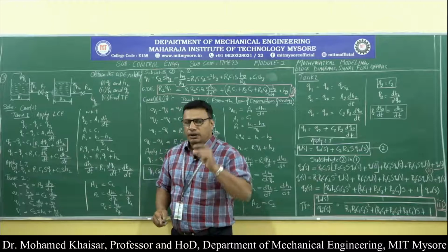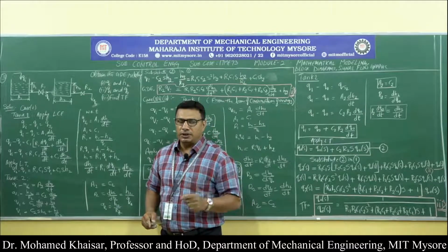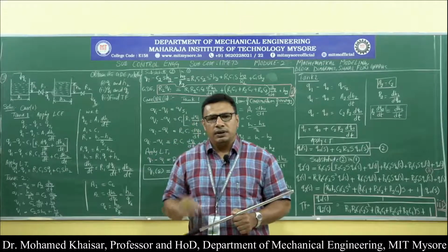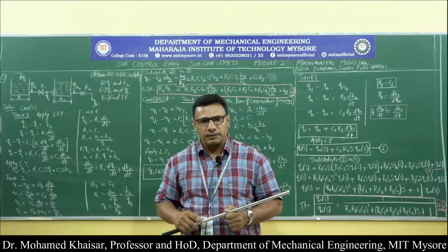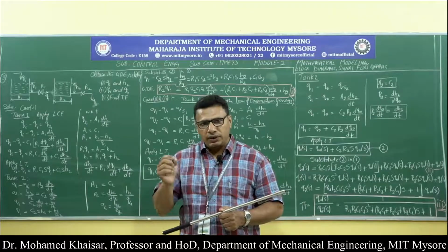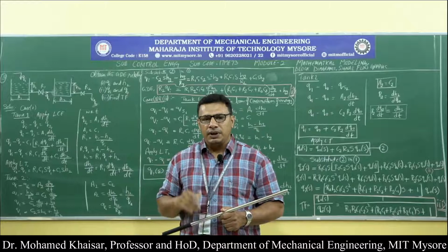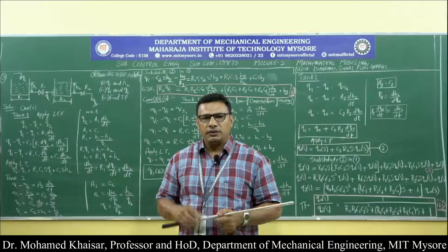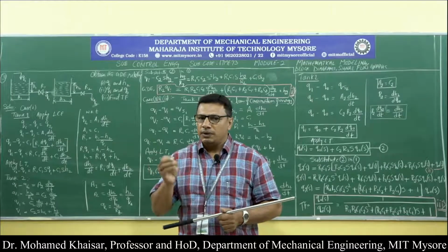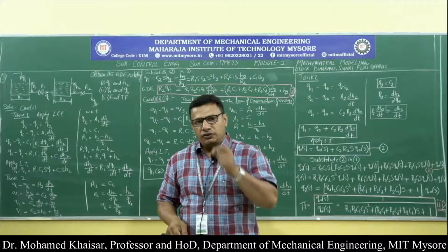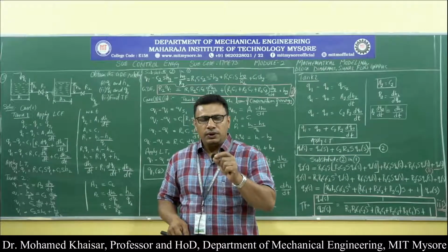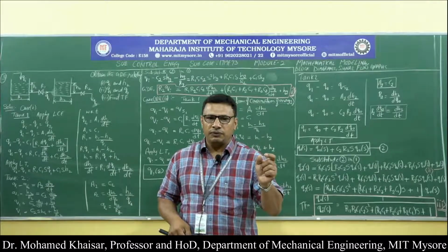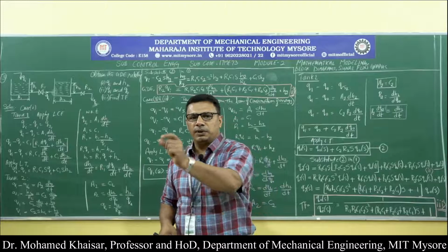Now, to make it easier to understand, an example I can quote is the mechanical systems wherein spring mass damper systems were considered. If there are 2 masses and one spring or damper is connected to both mass 1 as well as mass 2, what did we used to do? The resisting force offered by the spring will be the stiffness of the spring times the displacement of mass 1, if we are considering mass 1, minus the displacement of mass 2.